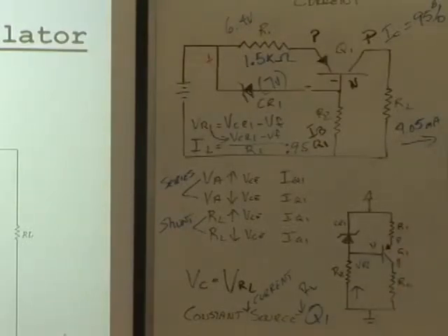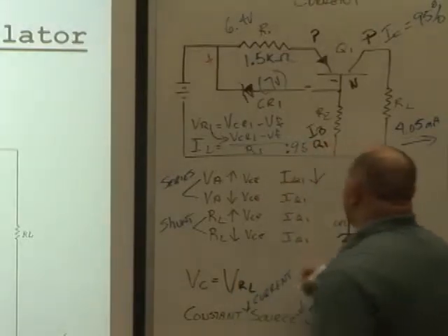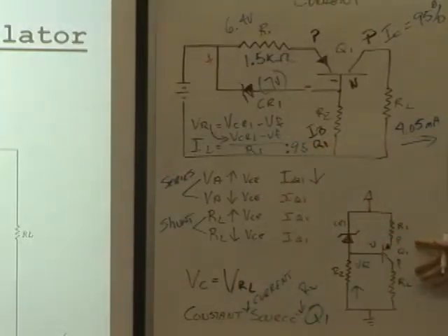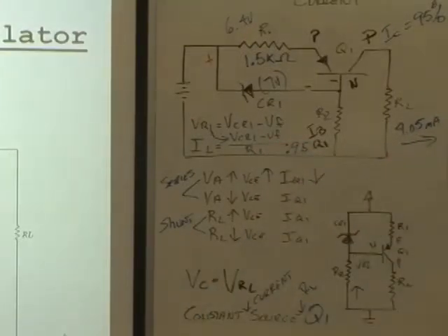NPN. So if I apply a large potential on the base, which is N-type material, what's the transistor going to tend to do? It's going to conduct less. And look, there's the proof right there. The base voltage increased a little bit, didn't it? Yes, sir. So it's going to conduct less. Naturally, the VCE is going to do what? Increase.